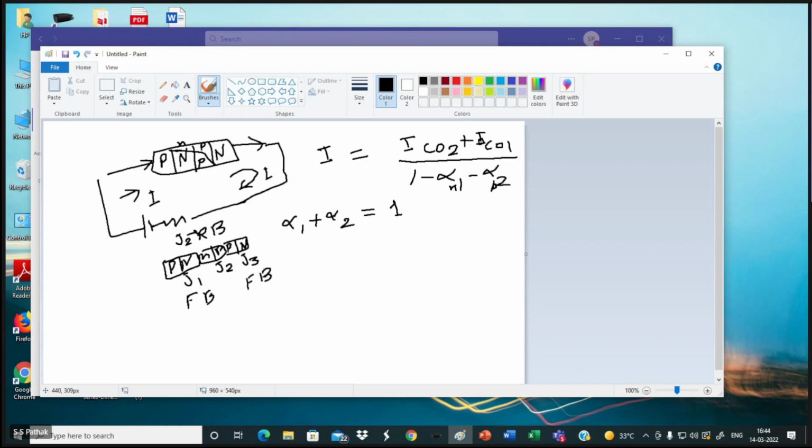So when heavy current flows, this forward bias is as such no problem. It will be working fine. Now this one will go to some kind of breakover region. I cannot say breakdown, that will damage it. It is going to break down actually, junction is going to break down, but for the device it is breakover region, breakover. So this J2, in this case, J2 becomes breakover.